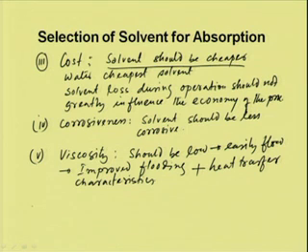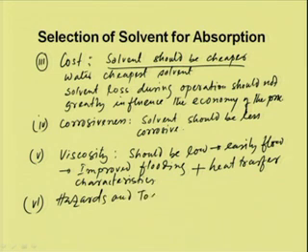And another important point is hazard and toxicity. The solvent should not be toxic and hazardous in nature, and it should be non-inflammable. So, while selecting a particular solvent, we need to consider these properties when the purpose of separation is to remove a certain component from the gas mixture.